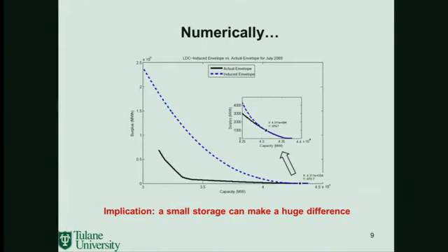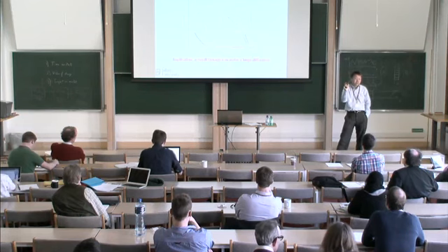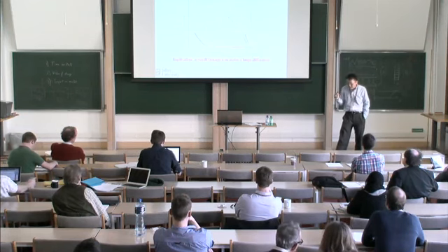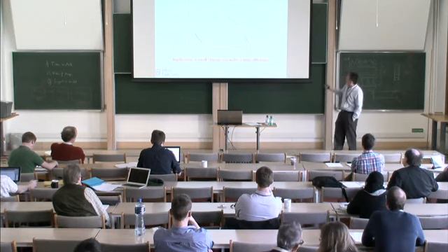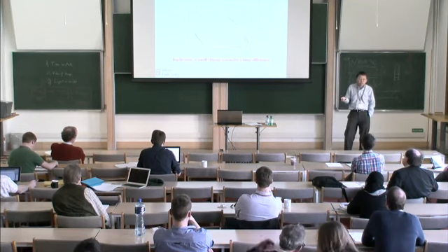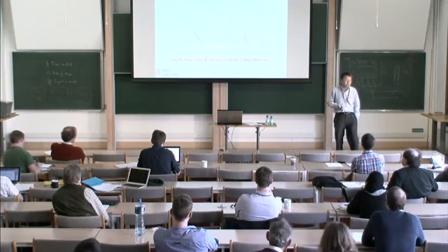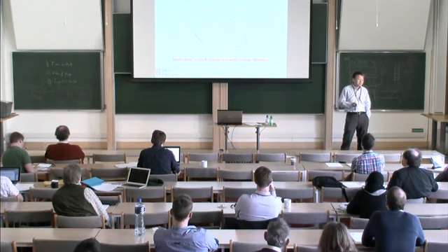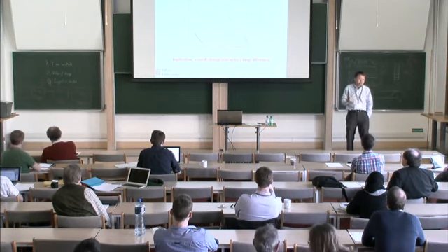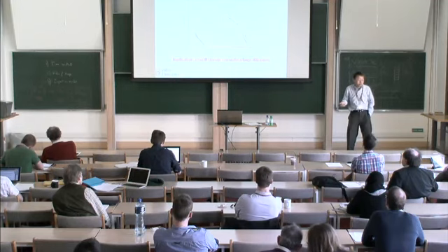However, one specific piece of information I hear, I can immediately respond to: they want to do 16 hours in terms of the ratio between the energy and the capacity. Immediately from this picture, we can respond, no, we only need to have like 4 or 5 hours. 16 hours is way too much. So you can use your money in a much better way to adjust the ratio. So essentially, this is what I want to talk about.